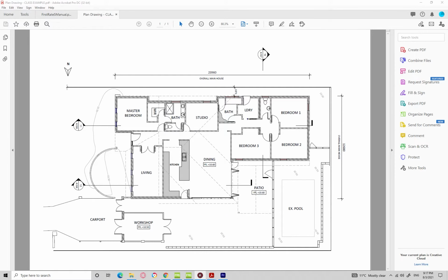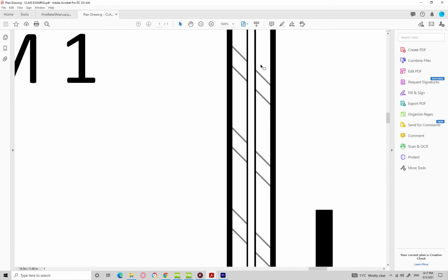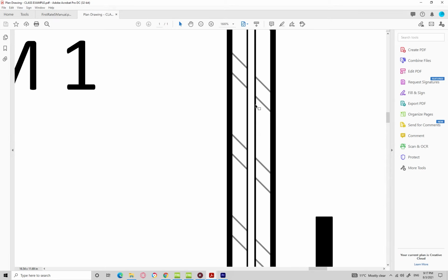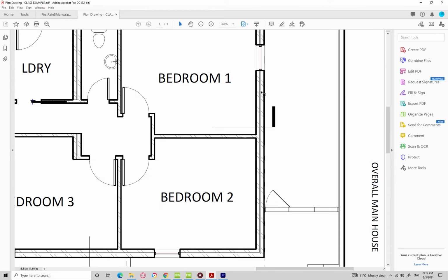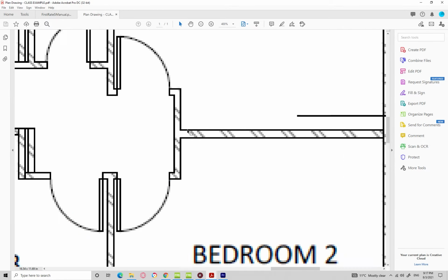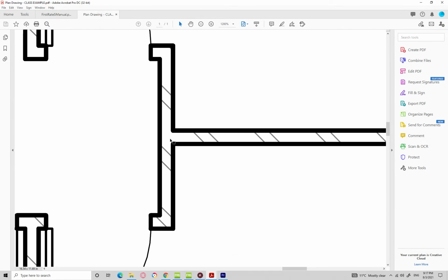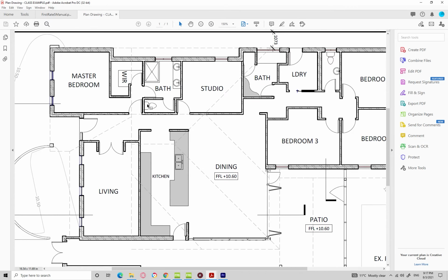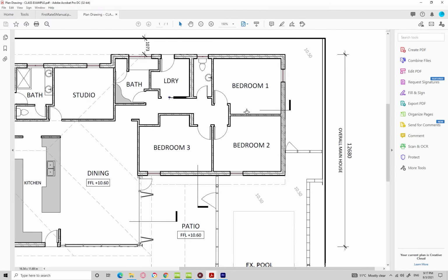in this house here, what we can see in the plan that I have provided you guys, we can zoom in and see these external walls here. They are double brick cavity walls. You can see there's an external brick leaf here, an air gap, and an internal brick leaf. Meanwhile, the internal walls that we see here, they are just single brick internal walls. So that gives it away for us. This is what this house is made of. It's a brick wall house.